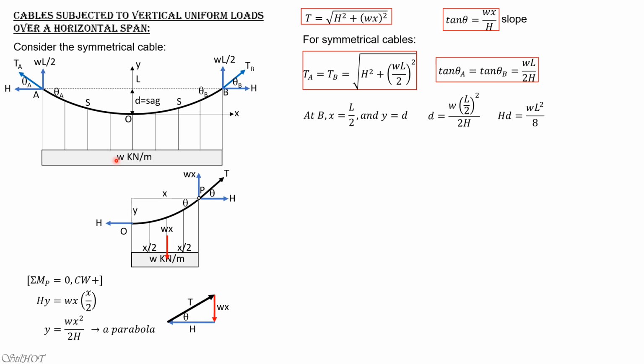So I hope that you know that the maximum moment in a simply supported, symmetrical beam loaded with uniform load across the entire span is WL squared over 8. So that's it. Actually, this is the general cable theorem. I hope you won't find trouble in remembering this relationship. So the formula for H is WL squared over 8D. That's the formula. And if you mind, that's constant here.